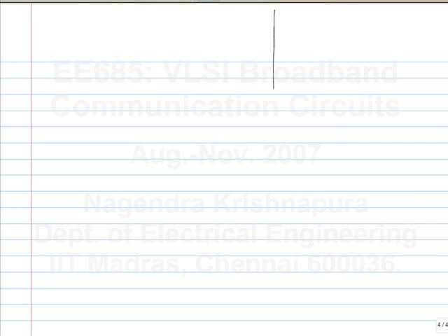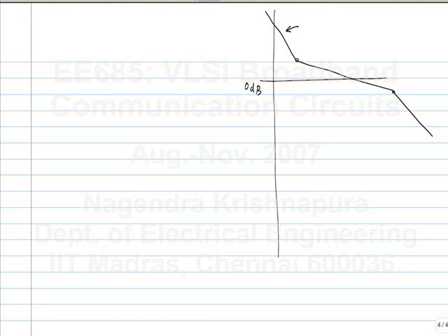Okay. So it is well designed, meaning if you plot the loop gain magnitude, it looks like this. And what is the frequency at which it crosses unity? Two pi kpd kVCO by n. Okay, this is omega, and this is the magnitude of the loop gain.